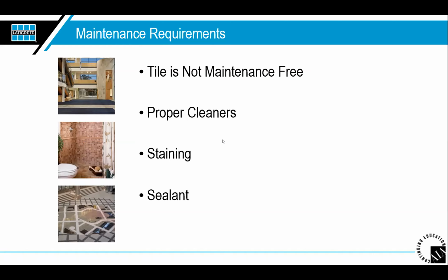So what's the easiest way to answer this here, and John, you may not know the answer to this, but was it actually considered like a control joint, or was it just an expansion joint, or do you know what the difference is? It was a control joint. Okay, so it was a control joint. So if it was a control joint, then yes, the TCNA manual is going to call out specific instructions for that. It does have to be honored through the installation, but sometimes we can actually put a soft joint, for example. It can go one tile to the left or one tile to the right.